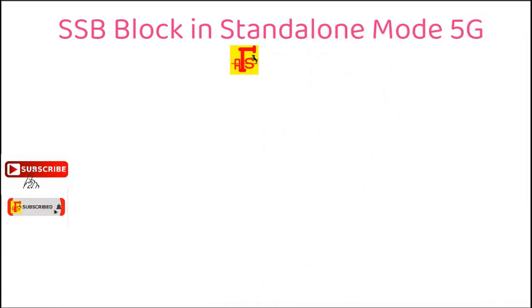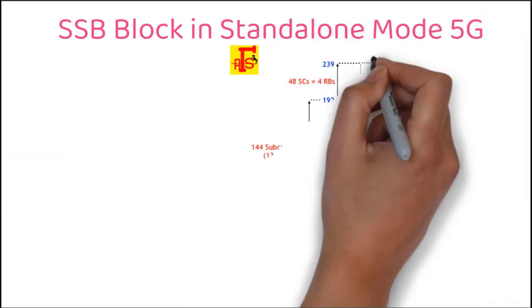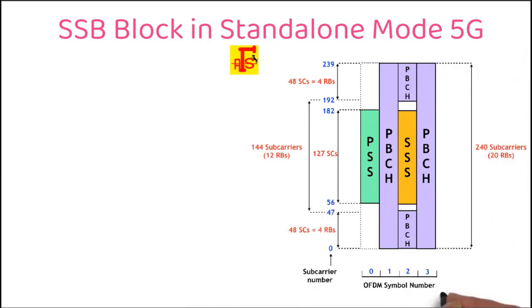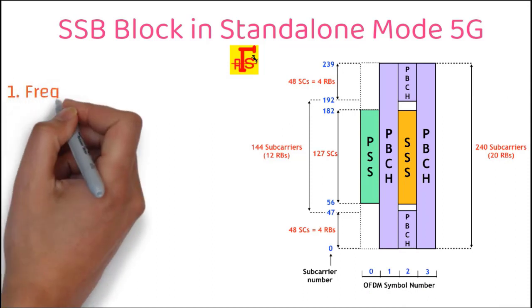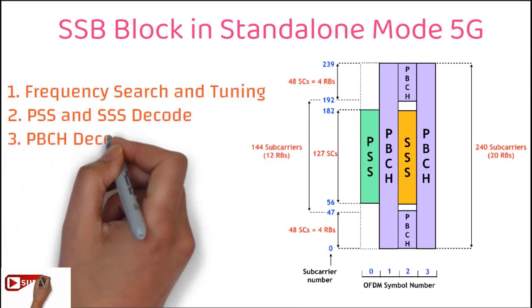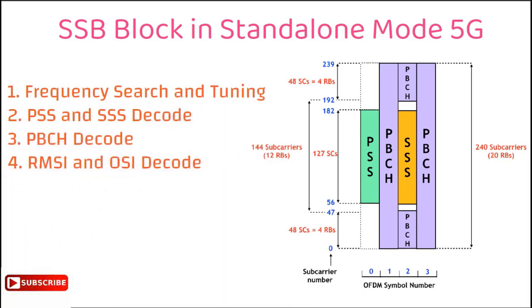Today I'm going to discuss the SSB block in standalone mode. In standalone mode, our cell search procedure follows these steps: frequency search and tuning, PSS and SSS decode, PBCH decode, RMSI and OSI decode.